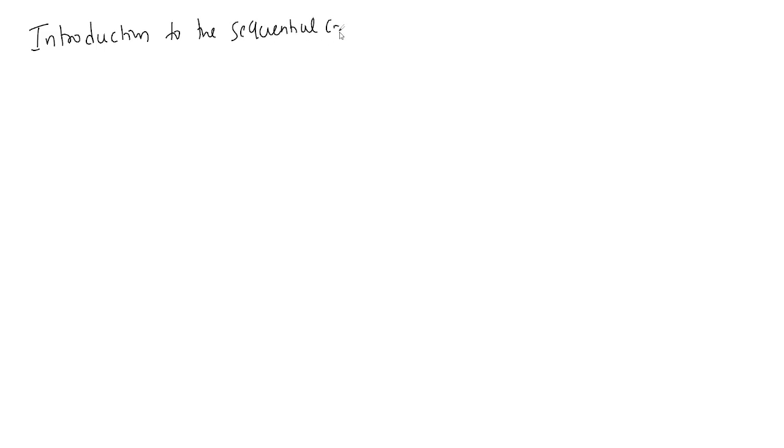If you see the sequential circuits, first we'll study the latches and flip-flops. Latches are nothing but level triggered and flip-flops are nothing but edge triggered. First I will write the code for the basic D flip-flop.